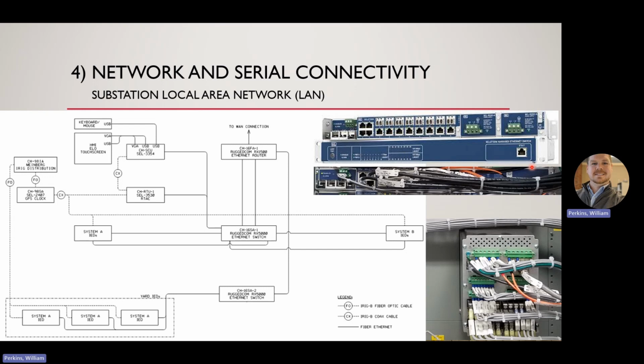Within the IEC 61850 protocol, that method of communicating to all of the IEDs at the same time is utilized. But in a non-61850 network, which is considered a conventional system, it's usually just the RTU communicating through the LAN directly to the IED that it wants to communicate to.